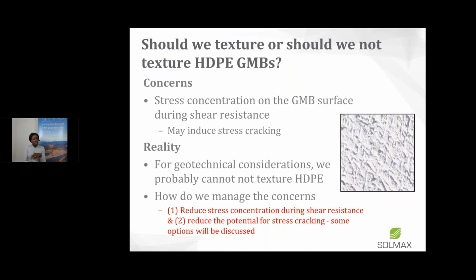The magnitude of the stress concentration, I don't know if anyone has ever quantified that, but that doesn't mean it's not a concern. It is a concern, especially if your asperity is higher, then you may have more significant stress concentration over the geomembrane surface.